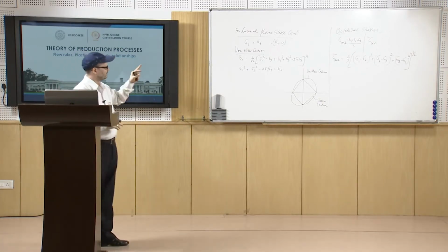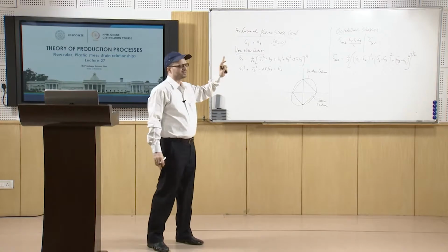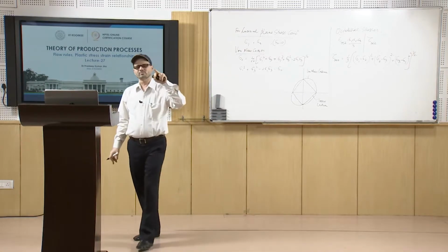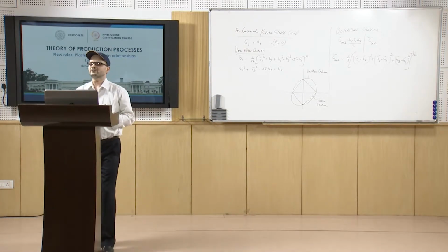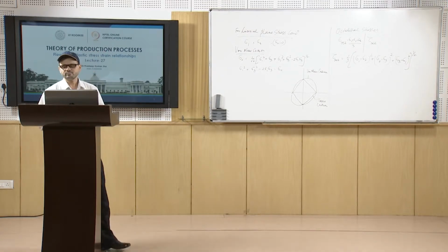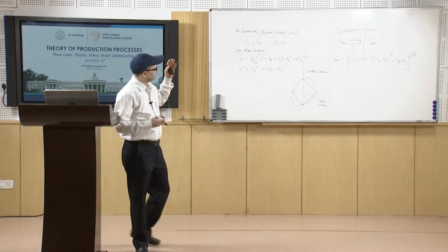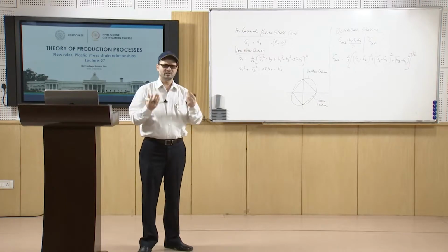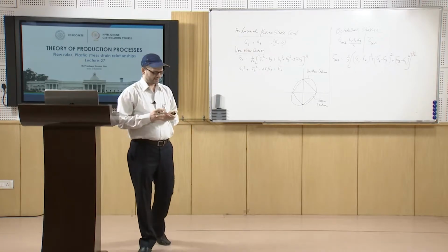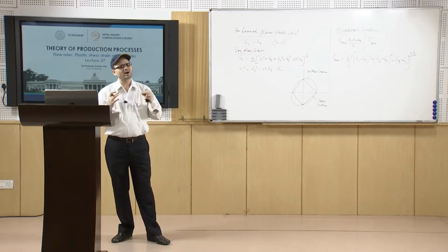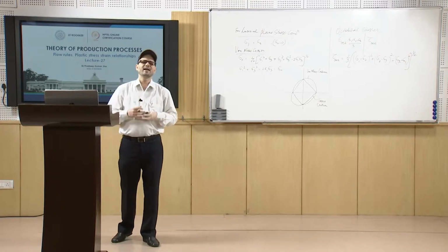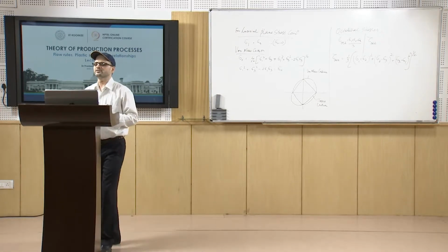Now, as we know, this octahedral shear stress is responsible for the plastic deformation. It is analogous to the stress deviator, because we know that only the stress deviator part is responsible for any kind of plastic deformation.